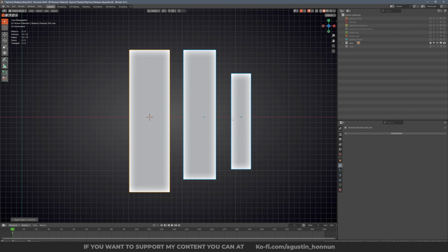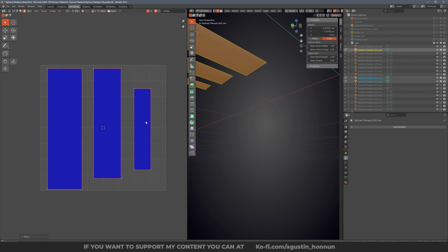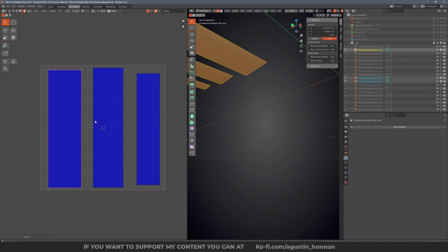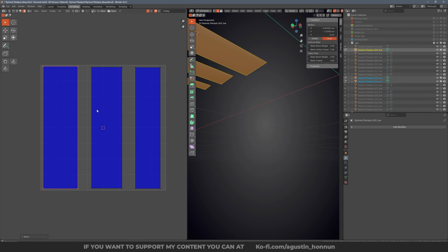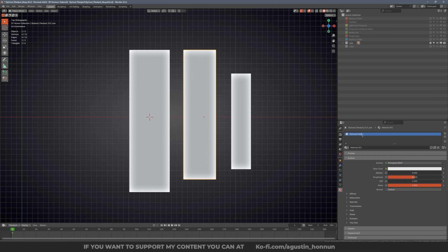Okay, now select those planes and just project from view. Go to UV editing, and here we can have the entire UV for these plants. Since I'm going to be using an entire material for these leaves, and I'm going to call these Stylized plant pot leaves matte. Select all of them, Ctrl L, and link materials. Now as you can see, they are in the same material.